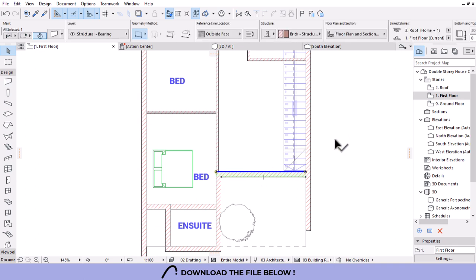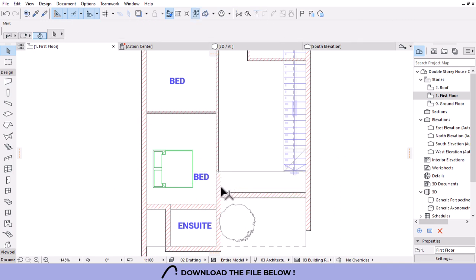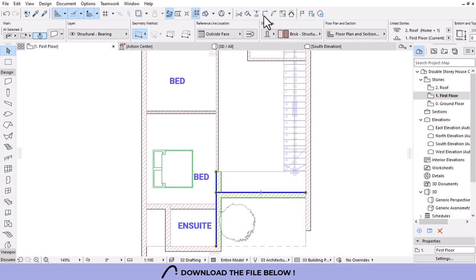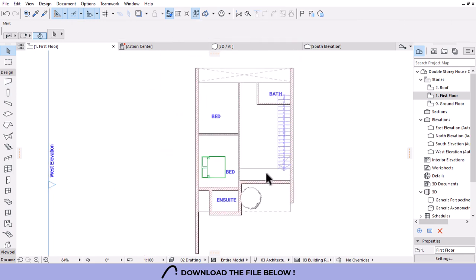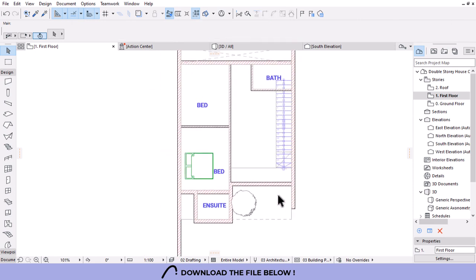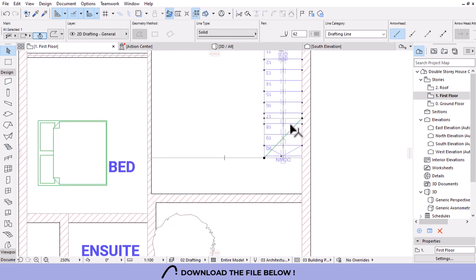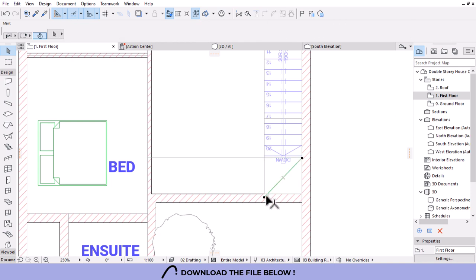It's either we move this wall by 1 meter, which is the size of the landing. So I'll say 1.1 or 1 meter. Move it here, and then let's fillet these two like so, and then we'll do the same to these two, just like that. Yes. So that when you start, you have the starter of the staircase, which is to the ground. So I'll move these elements to there, stretch it to there, just like that.